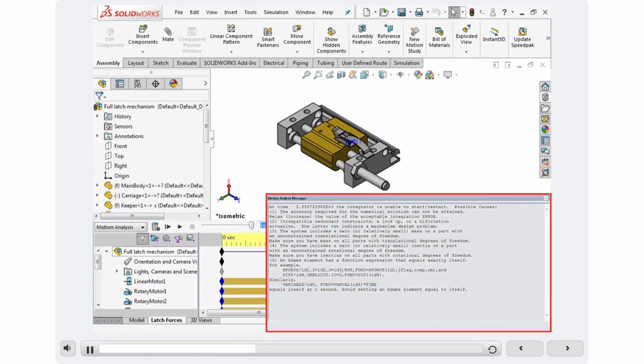As an approximate representation of the contact is being used, the solution may fail prematurely due to a lack of convergence. The simulation will fail and display the failure message. After reviewing the message, we can find that there are some possible problems. The first possible problem is that the solver fails to achieve the specified accuracy. We will try decreasing the accuracy of the solution.